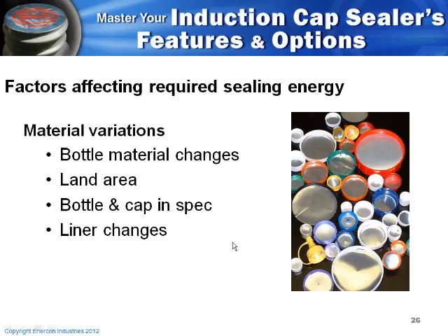The land area or lip of the container is also a very important piece. This is the part of the bottle that we're sealing to. The important pieces are that it's flat and even and consistent. You don't need a real large area. You can seal to about a 1 millimeter land area without a problem. But you'll want to verify there are no saddles or ridges in the land area. These are particularly common at the bottle part line.